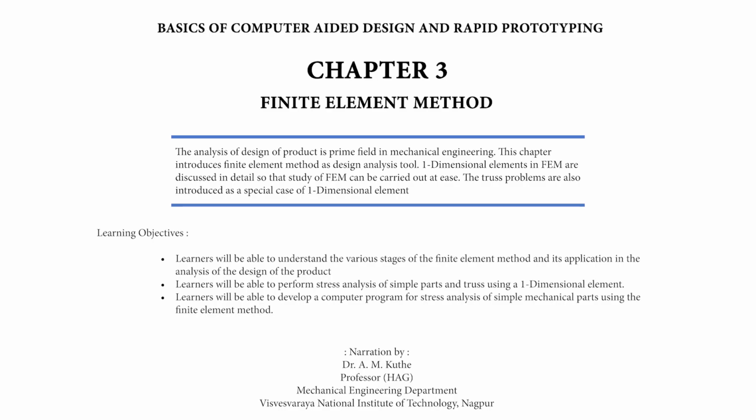Para 3.9. Assembly. Using the elemental matrix equation, it is not possible to get displacement at the nodal points of the element because the node is shared between two elements. In order to find the displacement at nodal points, it is necessary to apply the matrix equation to the continuum, which can be solved to get displacement at nodal points. Consider the stepped bar as shown in figure 3.13. In this figure, Q1, Q2, Q3, Q4 represent the displacements of the global nodes, that is nodes on the continuum, 1, 2, 3, 4 respectively.